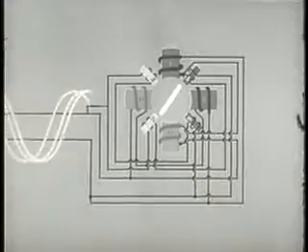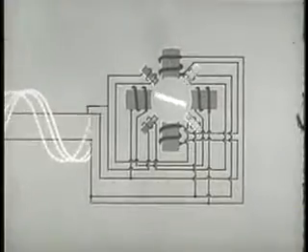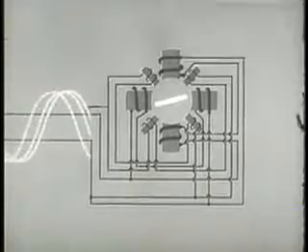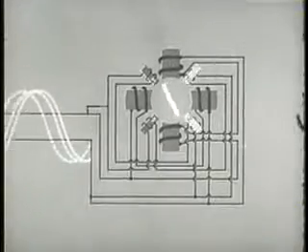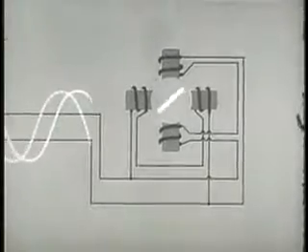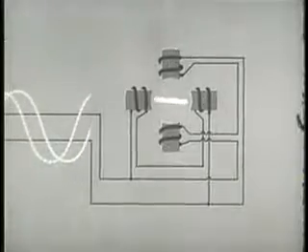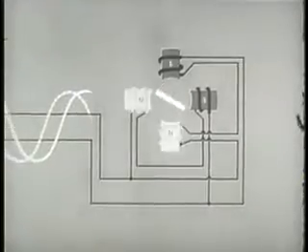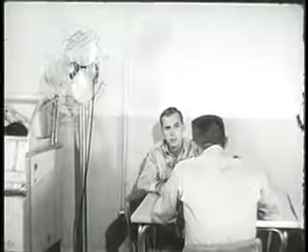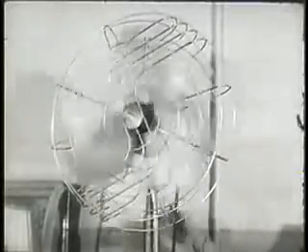The magnetic field now rotates electrically. The basic requirement of relative motion has been satisfied, and the motor has been started. When the rotor has attained approximately 25% of its rated speed, a centrifugal switch opens and disconnects the starter windings. The phase shift accomplished by the addition of starter windings is not very great. The starting torque in this split-phase arrangement, although better than that in the shaded pole motor, is still not too good.